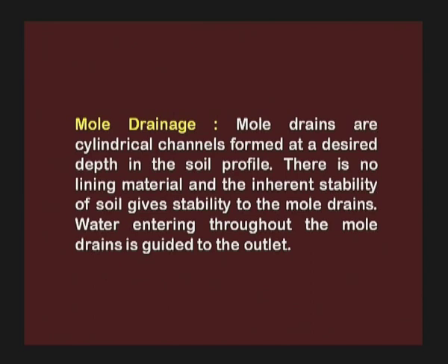Mole drainage. Mole drains are cylindrical channels formed at a desired depth in the soil profile. There is no lining material, and the inherent stability of soil gives stability to the mole drains. Water entering the mole drains is guided to the outlet. These mole drains are connected to each other and water is drained from the field.